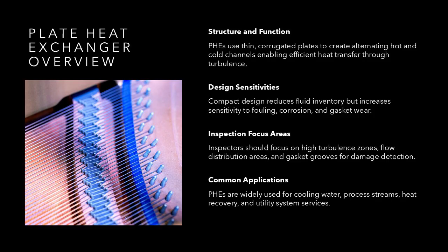PHEs consist of a series of thin, corrugated metal plates that create alternating hot and cold channels, resulting in high turbulence and efficient heat transfer. Their compact design leads to lower fluid inventory but higher sensitivity to fouling, corrosion, and gasket degradation. Common services include cooling water, process streams, heat recovery, and utility systems.